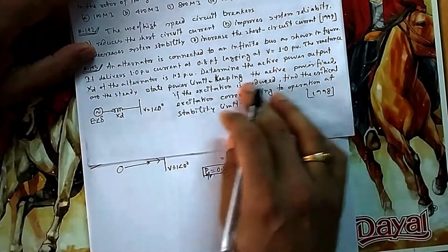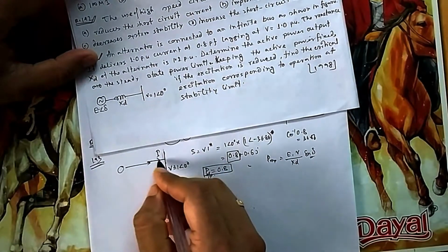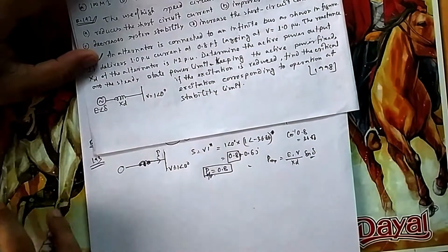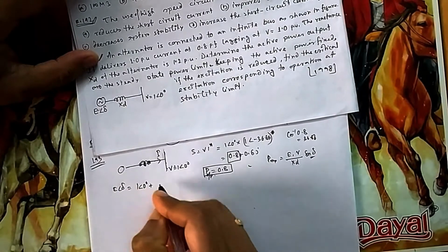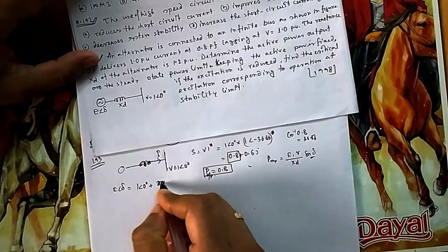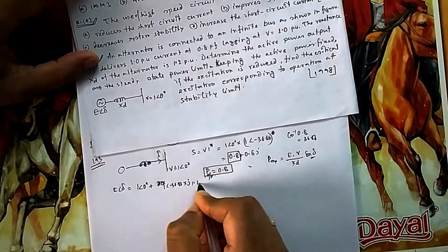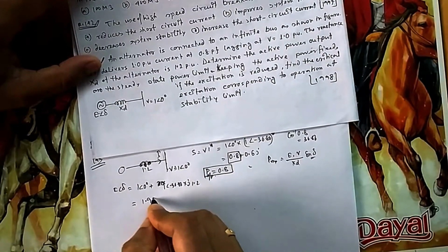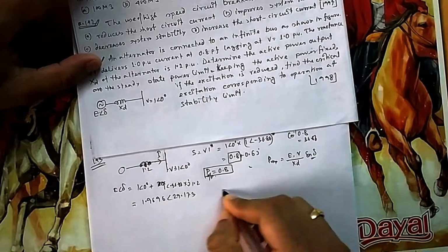Okay, so they have given you XD, that is 1.2. E you don't know, so E you can calculate. This current plus this voltage plus this drop will give you this one, E. So E angle delta is nothing but 1 angle 0 plus I into I is my 1 angle minus 36.86 into J 1.2, this 1.2. So if you do this one, you will find it is 1.9696 at an angle of 29.173. So you put it there.